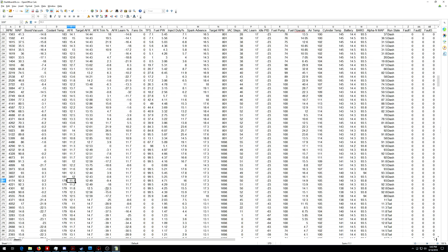You can see it's trying to lean it out, but by the time that happens, I'm basically at the end of the run. We're talking 4,200 RPM here to 4,500 RPM or so, 4,400, in the time frame it took to clean itself up. So it's happening quickly on the spot, but not fast enough to maximize your power.